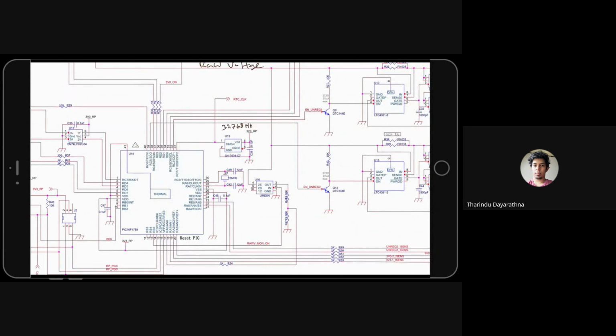That is not a good method because some current can flow in this path. Raw voltage is a different thing, it's a bus voltage. The reset PIC uses a different power supply after buck-boost converters at the end, so you should not directly connect it.